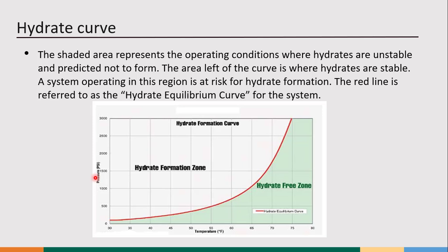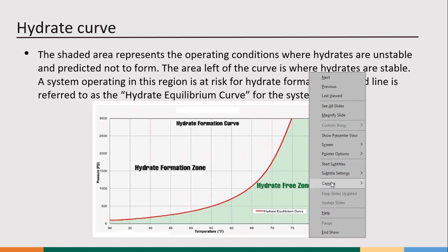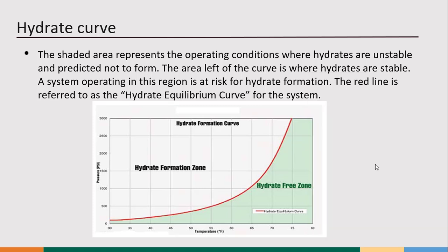Okay, when we talk about the chemical injection, what happens? There are softwares. This discussion is not about the softwares and how to predict it. We'll have a separate session for that. So if I put any methanol, some specific composition, I can shift this curve towards the left. So left means, after the injection, my curve will look like this.